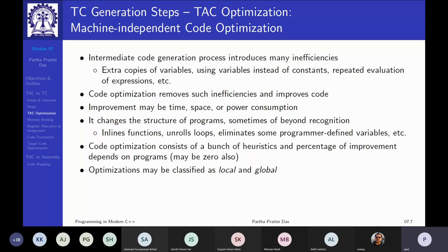Yes, that's one factor. But power is often a factor of changes that happen in the bits. If you do not change a bit, just hold on, then you don't consume power. But if you change a bit from 1 to 0 or 0 to 1, you consume power.